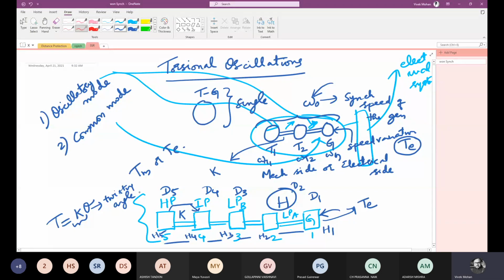Now, if we want to measure or quantify theta, how can it be done? We know that for the generator already we have an angular measurement which is in terms of del. Right? What is del? Physically, what is del? It is a relative angular displacement between the physical rotor axis and the magnetically rotating or synchronously rotating frame.